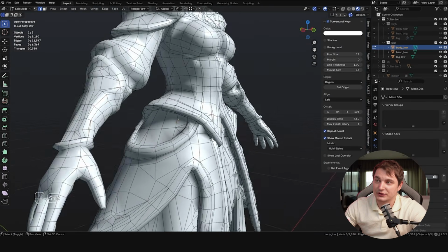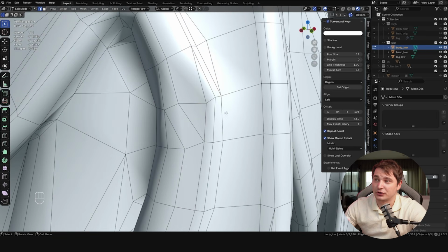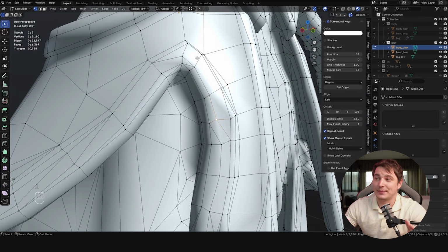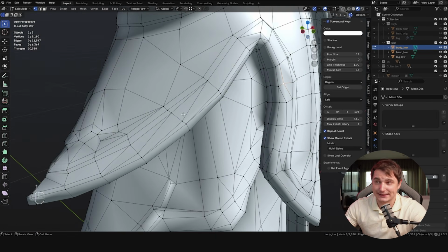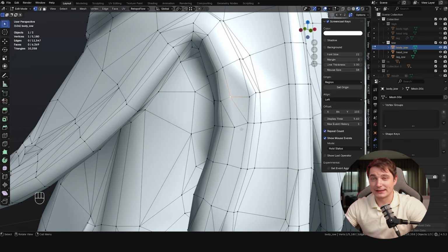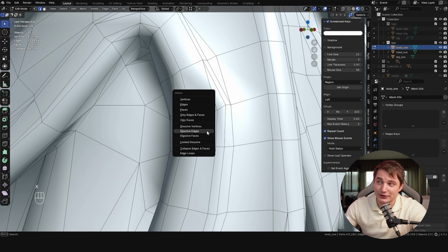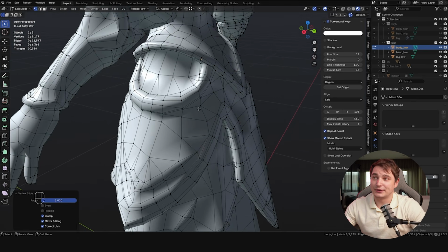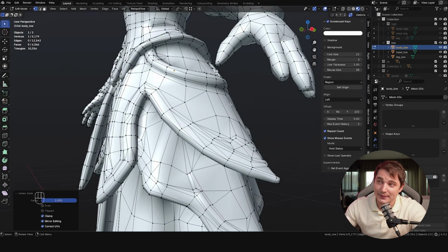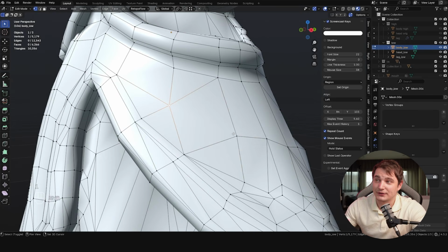So this model, it was generated in Tripo. It's actually a good job. Now the following issue here is that topology can be quite messy and loops might not be perfect and stuff. So here's my way to fix it, and we usually do that actually. So you can see this loop is not perfect. So what we're gonna do, we're gonna select two dots and press J to select two edges and just dissolve edges. With selecting two vertices, you can also merge them by pressing M and merge them at center and stuff like this.